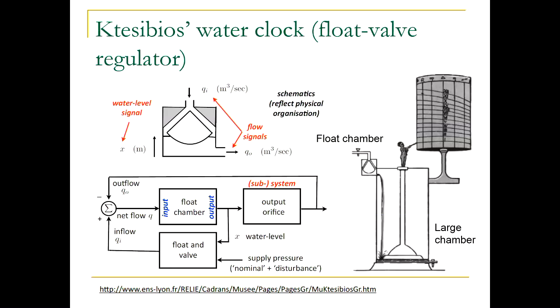So now that you've achieved the constant inflow of water into this tank, know that this tank would typically have this vent that's closed whenever this is supposed to measure time. And then, since the water inflow is constant and the cross-section here is constant, this float would rise at a constant pace. So it's proportional: the upward movement is proportional to time. And we will analyze this mathematically in a moment.